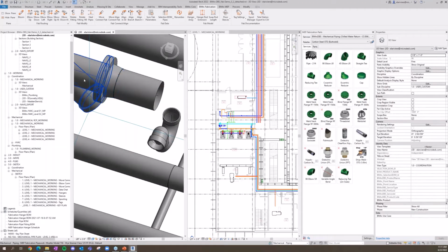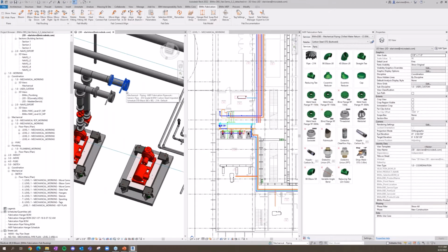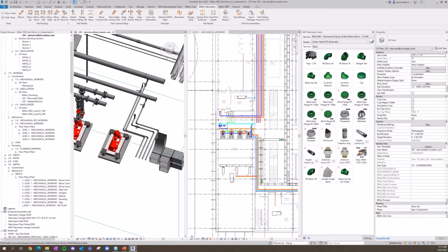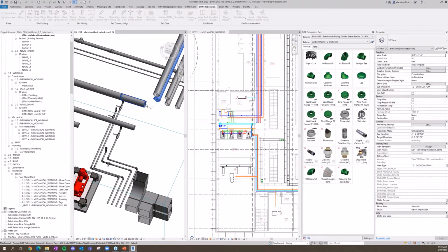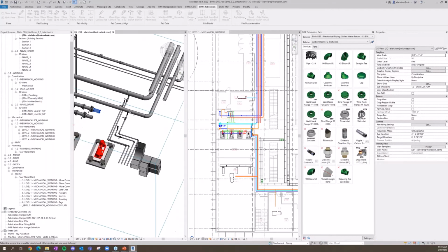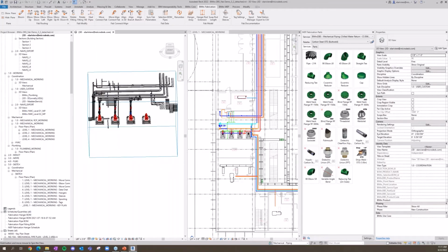Anytime we've got a service that's already got that information set up, we are absolutely following those routing exclusions to build these out. So yes, I am placing flanges as needed, and we can see that happen down here as well. Give myself an extension here and here. Now, if we take a look at some of these, they're going to be easy to connect. A couple of these I can probably trim the corner with the basic tools that already exist. But a couple of these two on the upper rack, not nearly as easy to deal with.